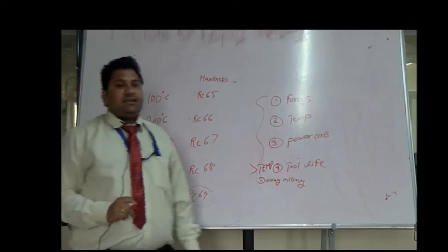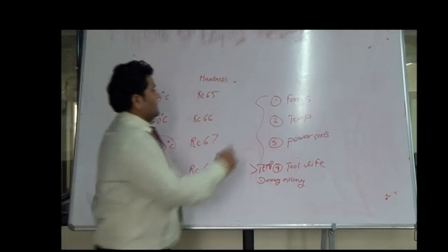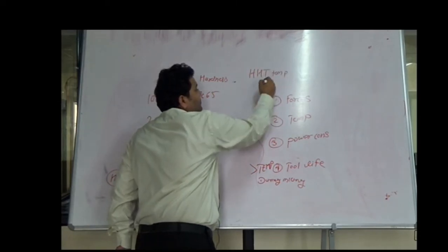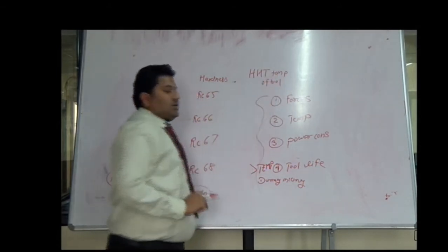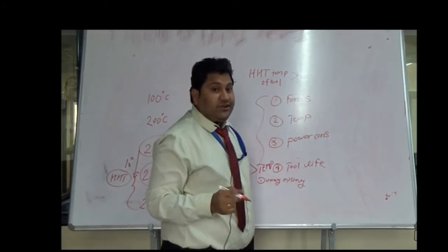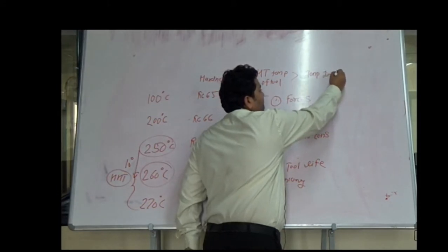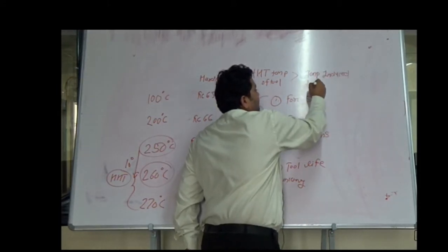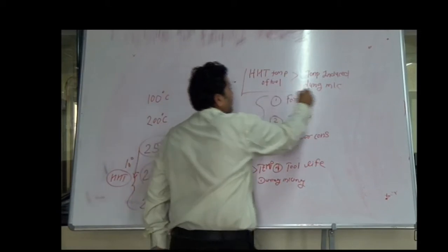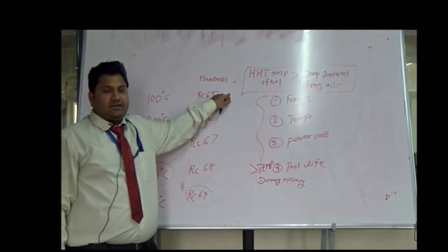So one requirement during the machining is about the hardness temperature. What is the requirement? The hardness temperature of the tool must be greater than the temperature induced during the machining. If this criterion is fulfilled, then definitely your machining is properly done.